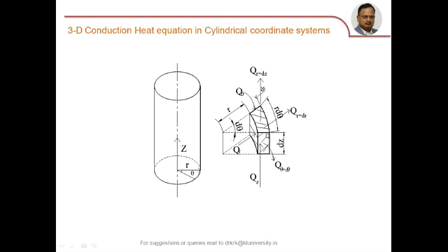Let the amount of energy stored in this element be m c_p dT/dt, where t represents time, the rate of energy storage. So, energy entering the element is equal to energy stored in it plus energy leaving.